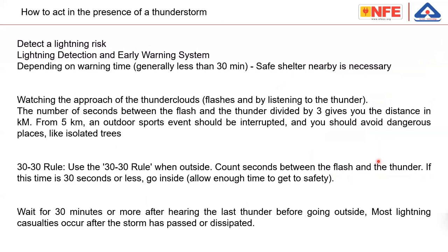How to react during lightning? The standard explains how to detect a lightning strike. Lightning detection and early warning systems are always available, or are already available in India. There are several agencies giving this information. I think ISRO has it, and the IMD has some app or something like that. You can register through these websites so that you get a warning. Generally, you need a warning at least 30 minutes in advance, because these 30 minutes are required for you to move to a safe shelter. If you are in the open outdoors, then you are in trouble.